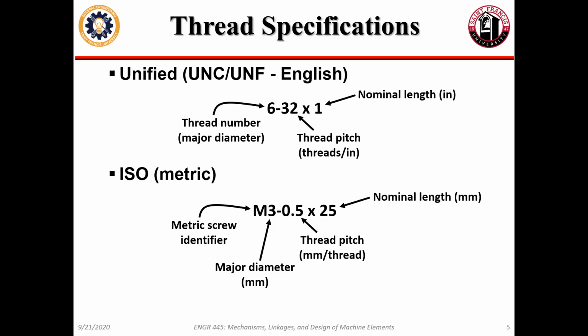you have a crap ton of thread standards out there, and the trick for getting any of them to mate is based on the thread angle, the pitch of the threads, the diameter, and whether or not it's tapered, and if so, how much it's tapered. So when you read these different standards and when you want to mate parts together, it's something you have to keep in the back of your mind.